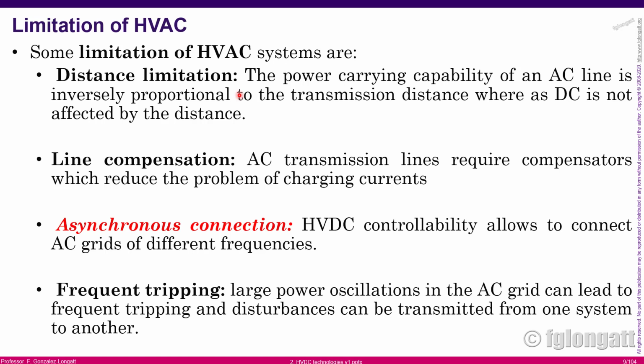Okay. Another interesting thing is that when we are using AC transmission lines, the classical AC, the connection creates a synchronous connection. From one point of view, that is quite interesting, because all the systems share the frequency, and the frequency moves through those AC cables. And for some purposes, that is quite good. I mean, everyone having the same frequency. But one advantage of the HVDC system is that those converters take AC signals and convert them into DC. And if those converters are appropriately located, they can create an isolation in terms of synchronism.